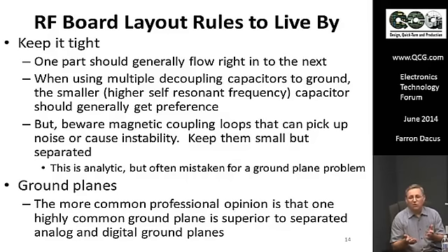In sophomore level network theory, they usually introduce this concept of mutual inductance. So, an ideal inductor will have a coupling coefficient, usually use the letter K for this, of 1, and then as you get these loops farther apart, they couple less and less, or their mutual inductance is going down, and they're not transferring as much energy via magnetic field. But in RF here, we're looking for stuff that's perfectly isolated.